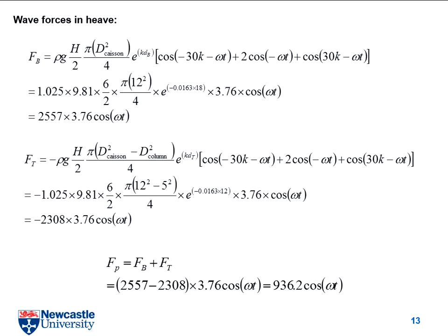So, after you know your waves, you can just apply the dynamic force on the center point. That's the pressure on this point. And because it's acting in this way and the diameter is quite small compared to the wavelength, we can just assume that on the whole surface, the pressure is all the same. So after you have the pressure on this point, and after you know the area, we will have the force.